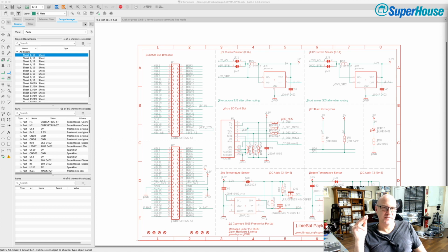Ideally what you would need is something like the equivalent of a two-way switch setup. So the way that works, if you have a long hallway, for example, and you want a switch at each end of the hallway, either switch can turn the light on or off. It doesn't matter which one you use. What they do is pass power in from one side into the common of one switch, and then you have the two switched outputs traveling the length of the hallway, going into the two switch contacts of the other end, and then you have the single common coming back out. And the result is that you can either make or break the circuit from either end.